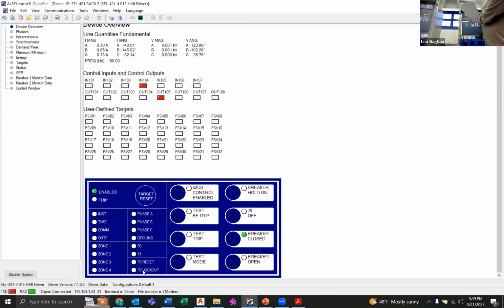So, okay. So now we can turn reclosing off. You'll actually see the act of turning reclosing off will drive that 79 to lockout. But you know that you can't reclose. But just for fun, we'll try a test trip and see what happens. So we tripped, and yeah, this one we're not reclosing.